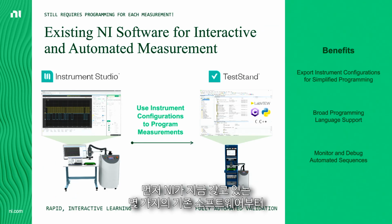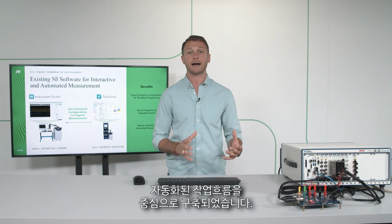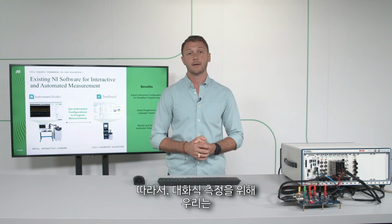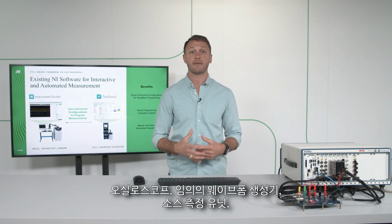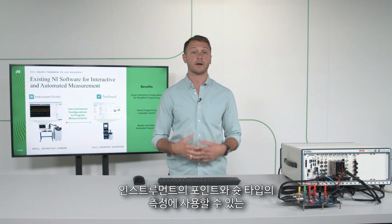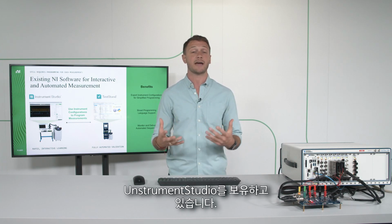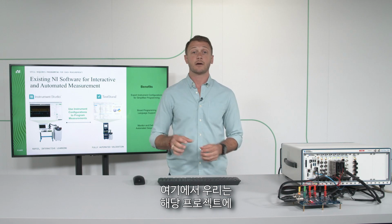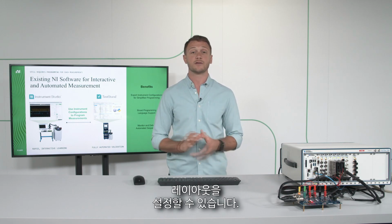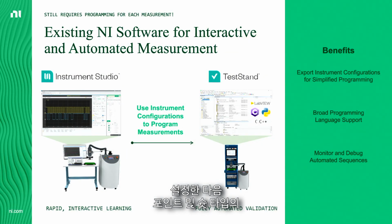First, let's start with some of the existing software that NI has today. And it's really built around this interactive to automated workflow that I've talked about. So for interactive measurements, we have Instrument Studio, which is our interactive instrument cockpit that you can use to make point and shoot type of measurements for oscilloscopes, arbitrary waveform generators, source measure units, digital multimeters, and other types of instruments. You can go in here and configure your layout with whatever instruments you would like to use for that project. You can configure the measurement settings like input ranges and sample rates, and then you can perform point and shoot type of measurements.